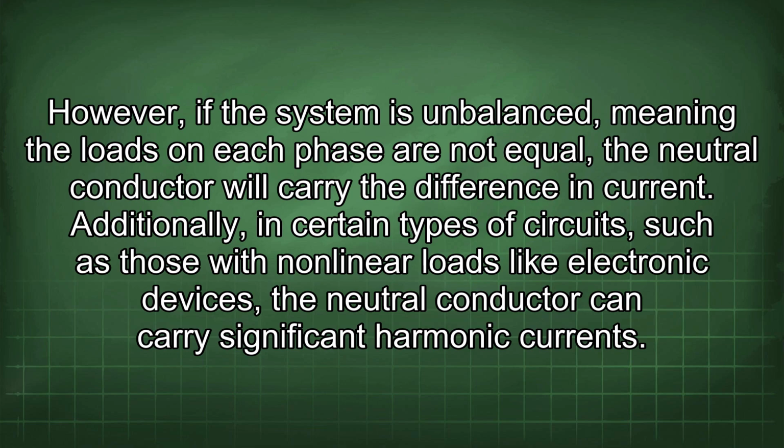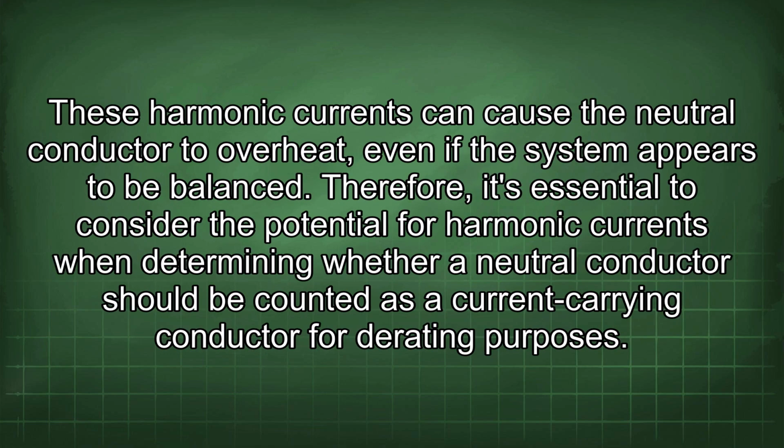Additionally, in certain types of circuits, such as those with nonlinear loads like electronic devices, the neutral conductor can carry significant harmonic currents. These harmonic currents can cause the neutral conductor to overheat, even if the system appears to be balanced. Therefore, it's essential to consider the potential for harmonic currents when determining whether a neutral conductor should be counted as a current-carrying conductor for derating purposes.